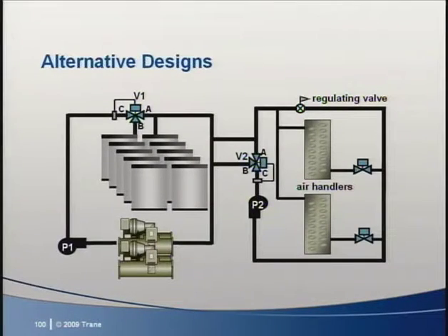The system doesn't change much with the chiller downstream. The only thing that changes is the colder temperature of the fluid going out to the coils during charge plus cool mode, because the chiller is downstream. V2 must blend fluid returned from the coils with fluid from the chiller in charge mode, which could be around 21 degrees. And notice this is a large design that requires glycol to the cooling coils.